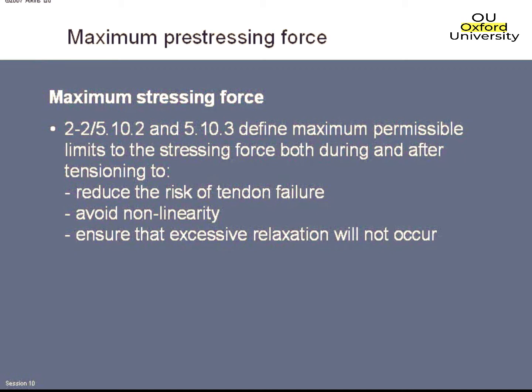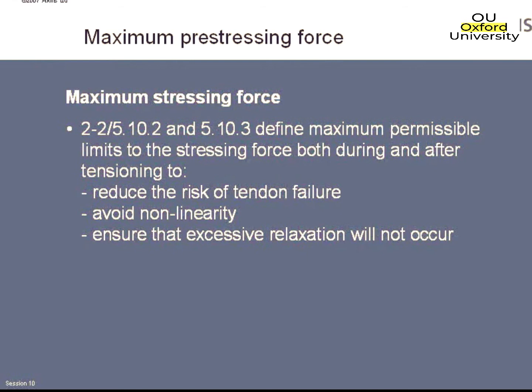And then thirdly, the other reason why we have to limit stressing loads is that the higher we stress the strand, the more unpredictable the relaxation loss becomes. So normally for pre-stressing strand, we quote relaxation at 70% of ultimate tensile strength, and that figure is usually quite robust. When you get to 80%, manufacturers will quote relaxation losses, but they become significantly less robust, and they could be actually quite a lot more than that particular figure. Obviously, the higher you go, the more unreliable that figure becomes. So there's another reason why we have to limit the stressing forces.